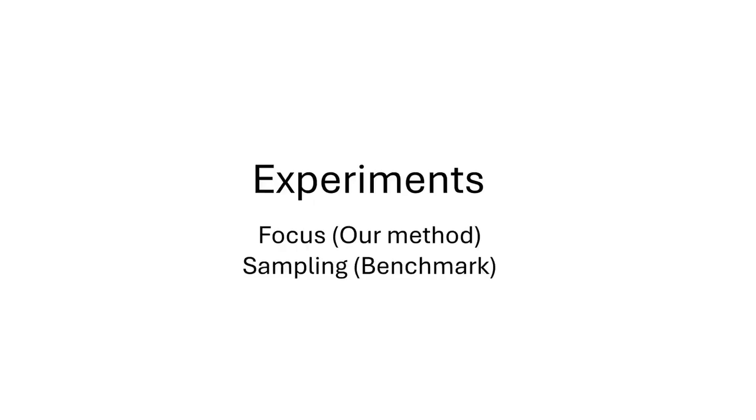We used the following 3 strategies while the robot moves between NBVs during the experiments. Focus. The robot keeps an informative focus point inside the camera field of view using our proposed method. Sampling. The robot uses an RRT star sampling-based method to plan an informative path. No path. The robot moves toward the NBV without focusing on any particular point.